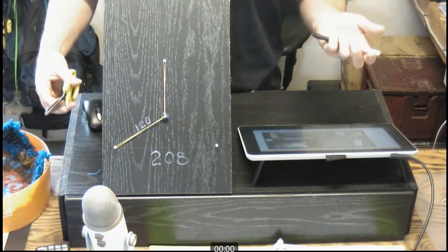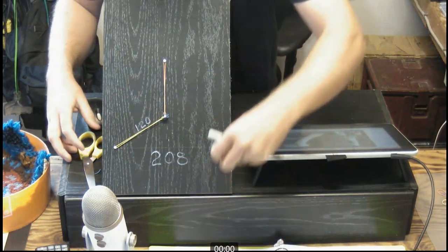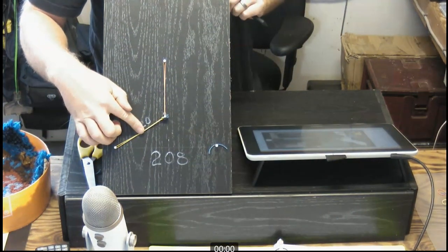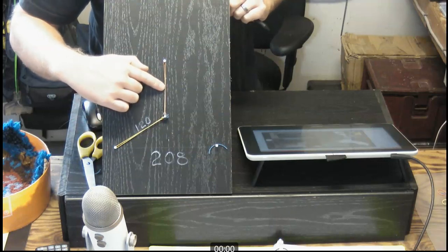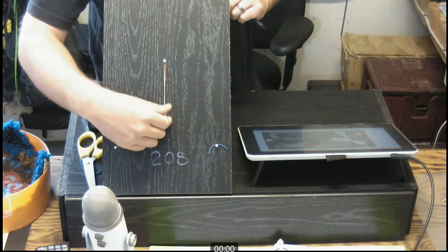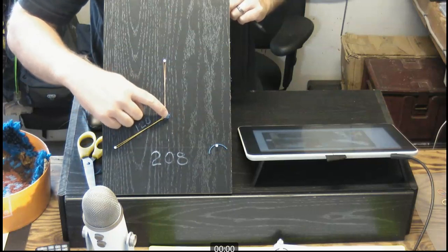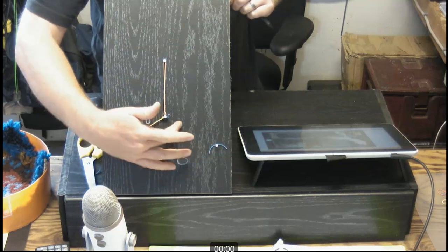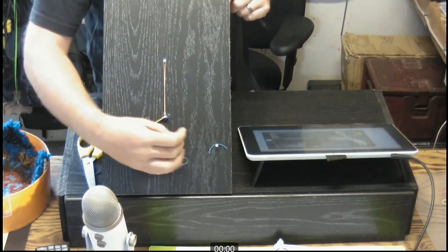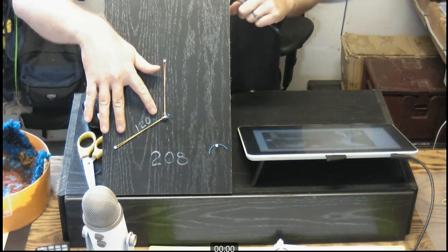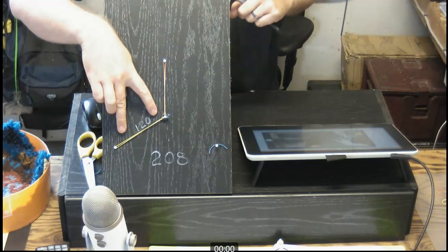We see that as soon as I cut, or as soon as I open that load up over here, I see that this load stays unaffected. I see that this load stays unaffected, but I see that this load over here does not have a complete path for current flow, right? I've still got just a little bit of blue over there and a little bit of blue over here, but there's no complete path for current flow, therefore we're not going to have any watts dissipated across it. This one is going to dissipate full watts. It's still got the proper value of voltage over top of it.